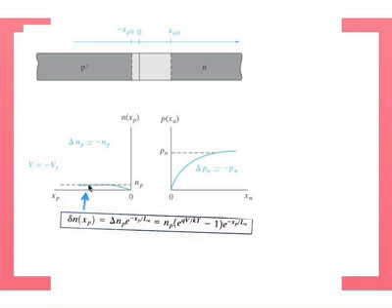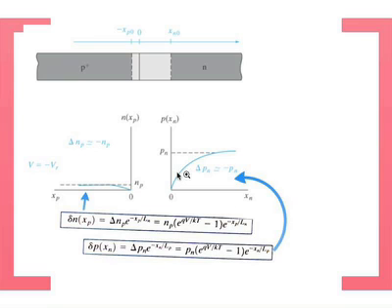Okay? This is basically explaining that. And you can calculate it in exactly the same manner as we did for the forward bias. You get the same kind of plot, but it's the opposite direction, that's all. Okay? So delta n_p times e raised to minus x_p over L_n, L_n being the diffusion length of the electrons, then you get an expression that depends on the voltage here. And the same thing happens for the holes, exact same expression.